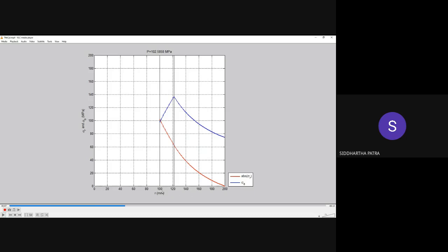So by the time we reach b, when C becomes B, we would expect that the stress right here is 138 MPa, according to your calculation, which is ln of b square by a square. Okay, so it is already 131, 132. One second.